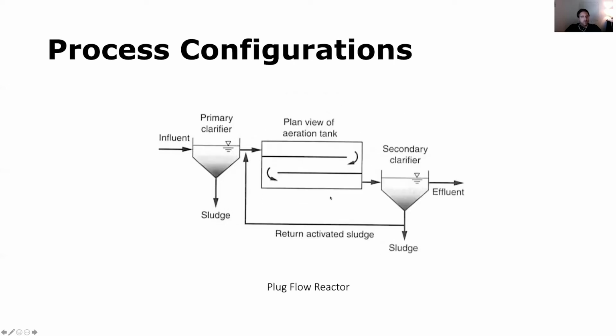We might also have some systems where the aeration tank is designed in a different way to try to achieve more of a plug flow regimen. So instead of complete mix, we have a little bit more like a plug flow reactor. But other than that, the process is essentially the same. The calculations, however, will be different because of the nature of the flow and the hydraulics.